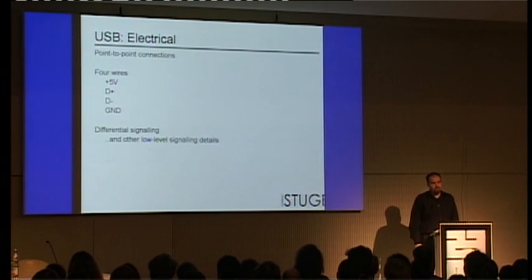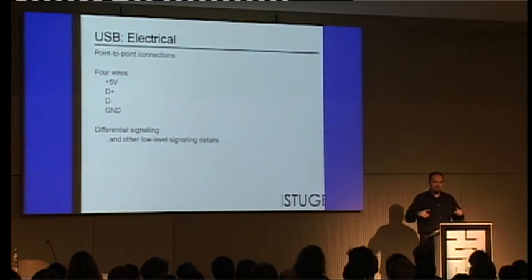Quickly for the others, differential signaling means that you have 2 signals that do the opposite. Instead of having one static signal and another which is the value, you measure the value by seeing the difference in these 2 signals. And the bonus is that if there's some kind of interference on this cable, then the interference is going to be the same on both wires, and then you can effectively cancel it out. It's the same principle also used in plain Ethernet networking.